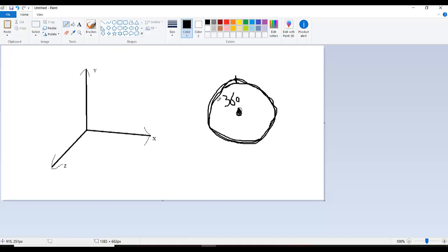So for the revolve command in Fusion 360, basically we make a sketch and then revolve that sketch around our axis. Let's suppose these are the three axes. If we select this XY plane, which is in front in Fusion 360, and draw a sketch on this plane, we can revolve it around the x-axis. The central axis of the sketch will be that axis.